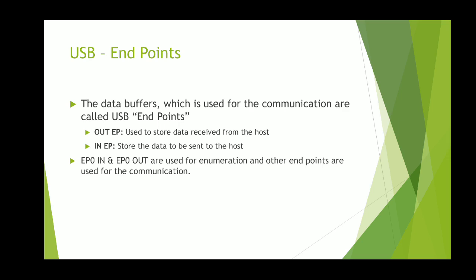And here endpoint 0 is used for control purposes, such as enumeration during the communication. So without this endpoint 0 in and endpoint 0 out, the device cannot function. And this endpoint 0 in and endpoint 0 out is never used for data communication purposes.